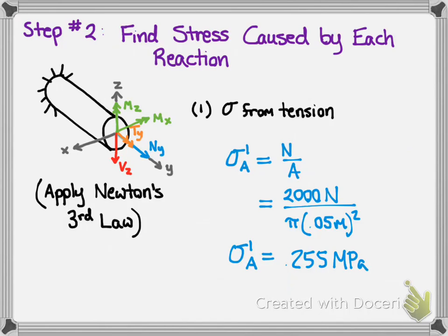So we also want to denote whether it's tension or compression. We can do that by sign, but it's easier for us to keep track usually if we simply write tension and leave all our signs positive. If it were in compression, I would leave my sign here positive. I would just write compression instead of tension here.